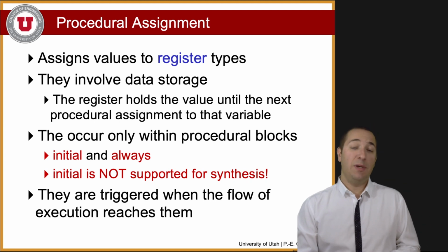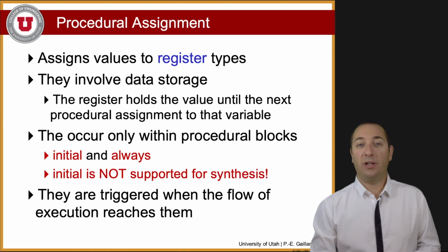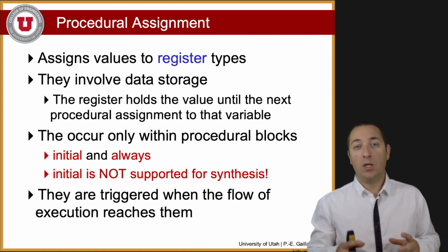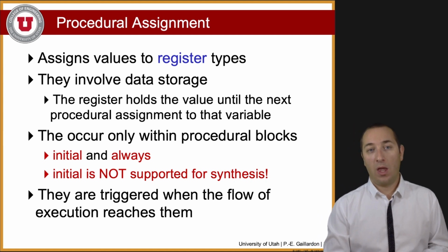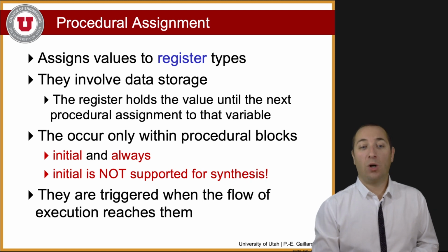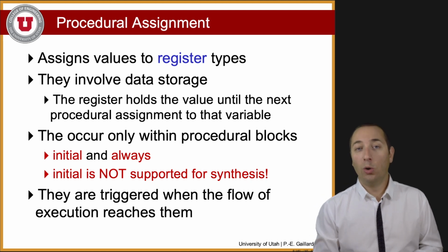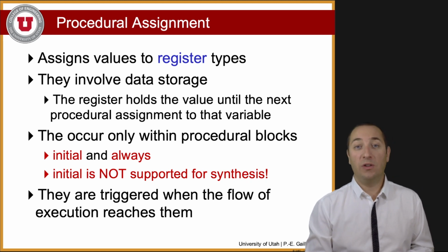And what does it mean? It means that the register will hold the value until the next procedural assignment to that variable. So we will keep this value until the next assignment is evaluated. And that occurs only within procedural blocks, which are either initial or always statements. Note that the initial statement is not supported for synthesis.